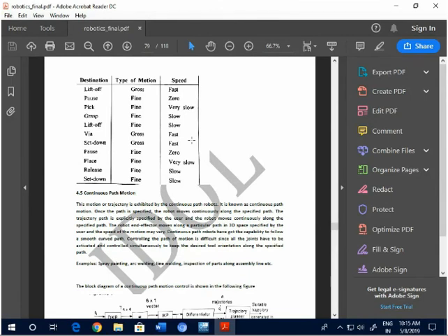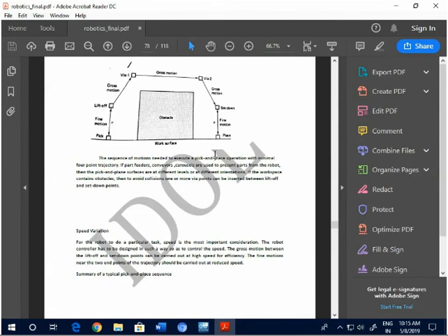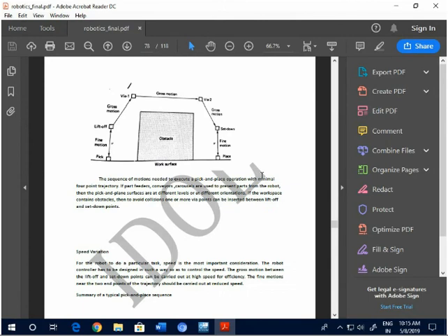Okay, so the area within the workspace envelope of a robot. Suppose this is my robotic arm, so my robotic arm has a degree of freedom and I can move only in this way, that is from this end to this end. So this is the area covered under this zone, my workspace. Okay, the freedom in which my end effector can move and perform some task is my workspace. So at present my hand is moving from this end to this end. So the degree of freedom is this much, and so this is my work envelope.